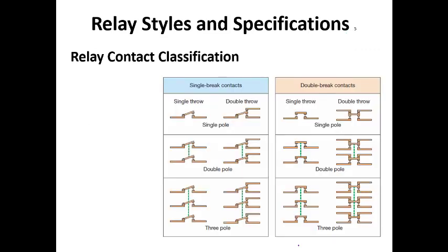Here's another example of some other circuits. This one includes a 3-pole circuit. So this would be our 8-pin relays are like this. So this would be the 8-pin ice cube relays we have. If we had an 11-pin relay, it would have this specification. This one here, which is a 3-pole single throw relay, this is what we would have on our contactors.